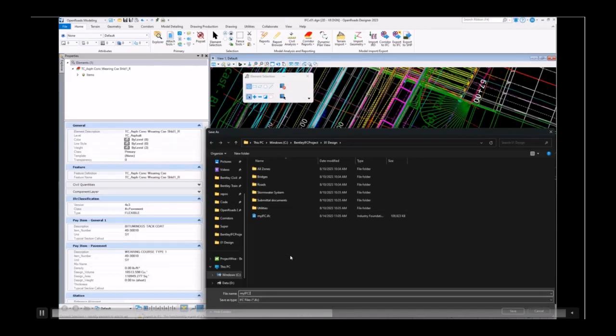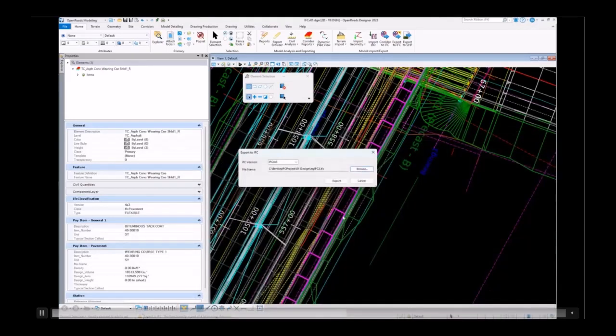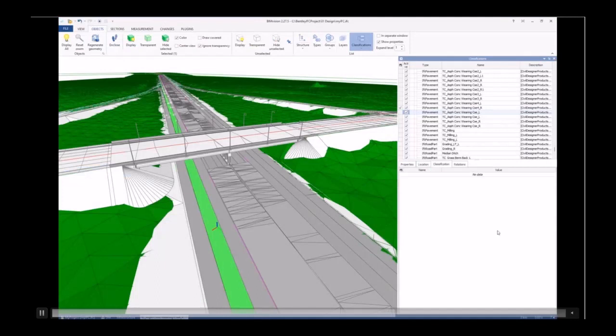Here we're just exporting. Once we've got our data the way we want it, we want to export out to IFC. We just select the IFC version, give it the file name, and you can see we now are looking at this through an IFC viewer like BIM Vision. So again, we can take it across as just generic building proxy, or we can be very specific with our classifications through the use of item type. So that tool is in 2023.